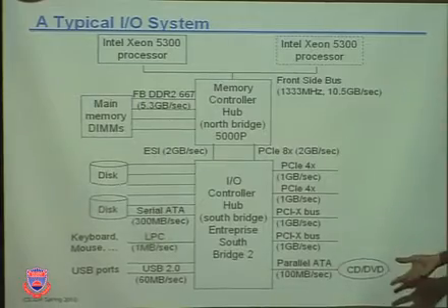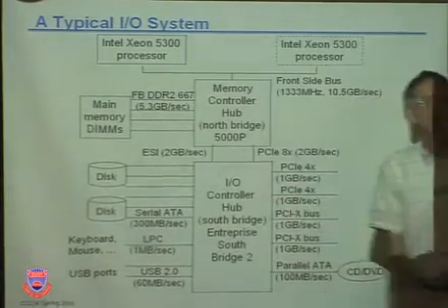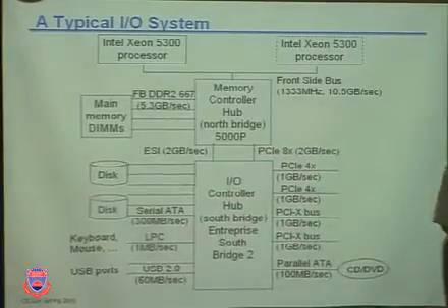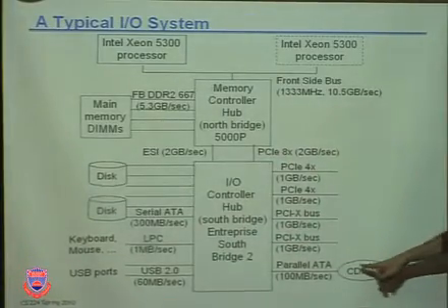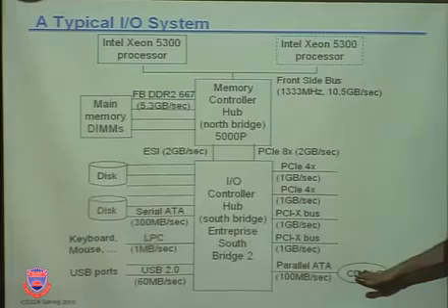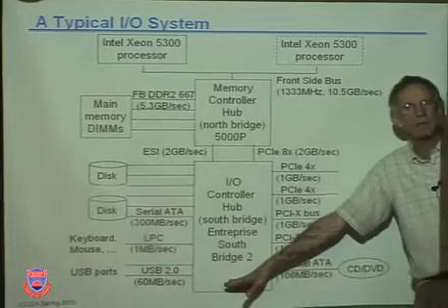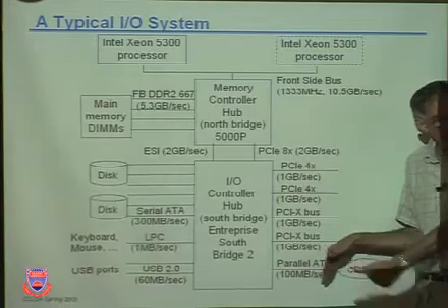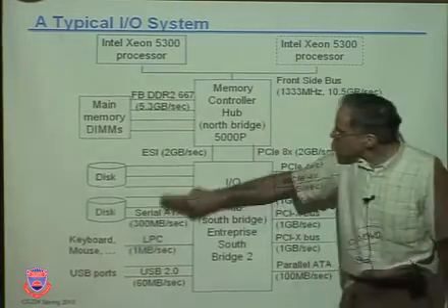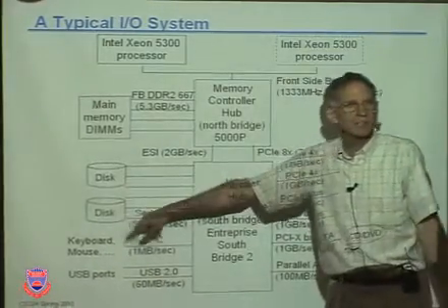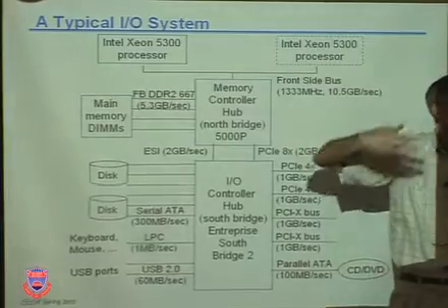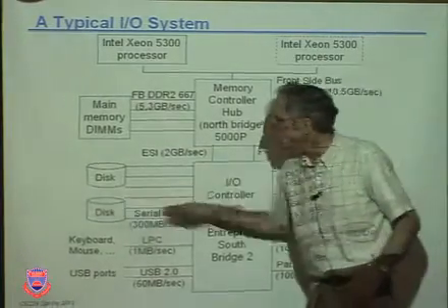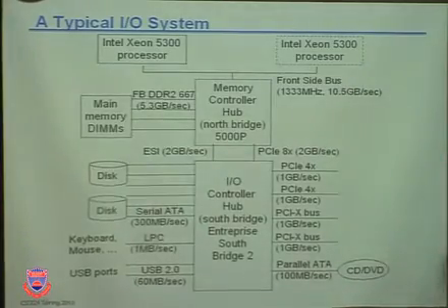All diversity, but this chip has been built to allow a certain number of this kind, this kind, that kind. So these buses really just have two members. One is the I/O device on one end, and the other is the chip on the other end, keeping the distances short, keeping the numbers of devices small. It's better to have two serial ATAs with different disks than one with two disks on it, right? So you can add these ports with transistors here cheaper and get better performance than putting two disks on the same bus. Anyway, that's an idea.